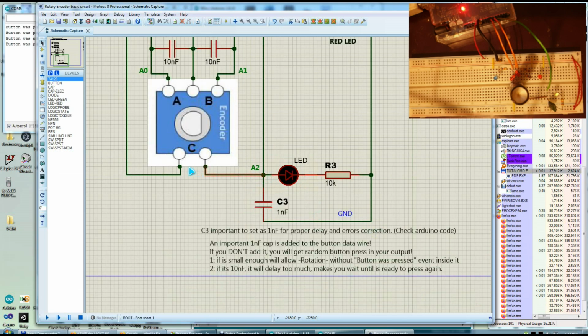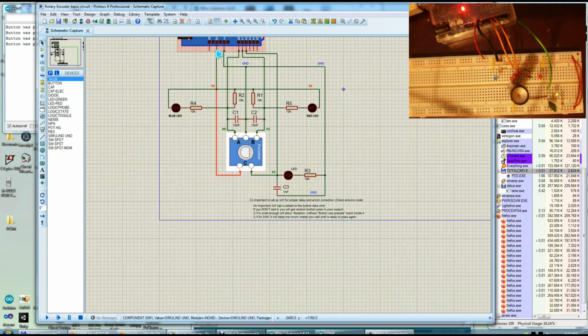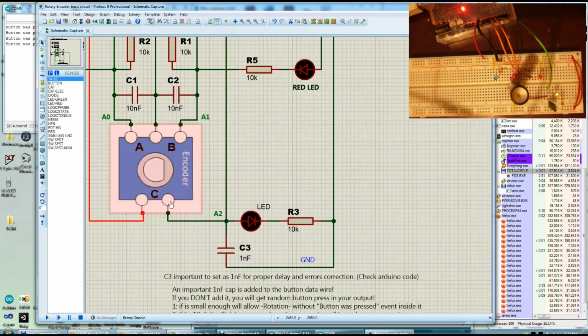So pretty much when I'm pressing this C button, the positive line, which is coming directly from 5 volts there, gets through the button when it's pressed, activating this data line as positive, but also lighting up this LED through this limiting resistor of 10 kilo.